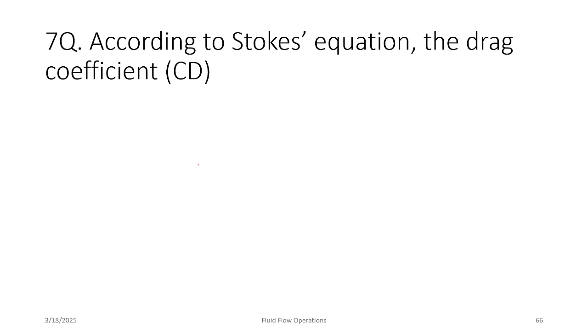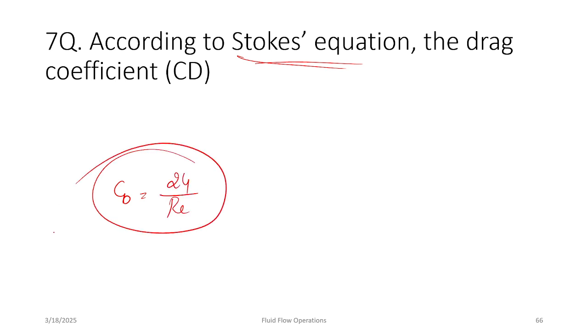Option B. So according to Stokes equation, the drag coefficient, what is the formula for drag coefficient according to Stokes equation? When do you use this Stokes equation? For slow flow over a sphere, right? So in that case, CD will be equal to 24 by Re, right?